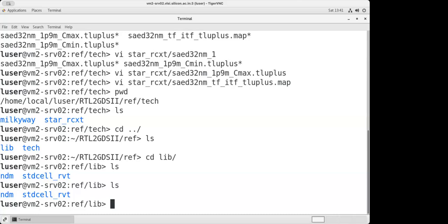So the foundry is going to tell you, okay, see, I can give you the options. Metal 1 to metal 4 with this kind of resistivity, metal 5 and metal 6 with a different kind of resistivity. You can choose any of these metal stacks. Metal stack in the sense, 5 metals placed one above the other.